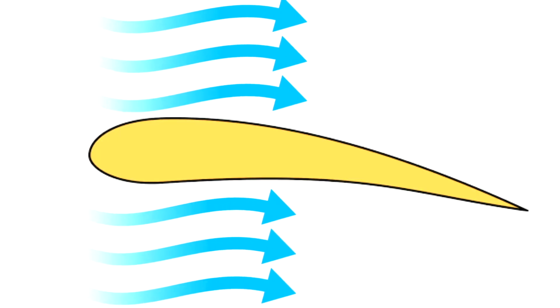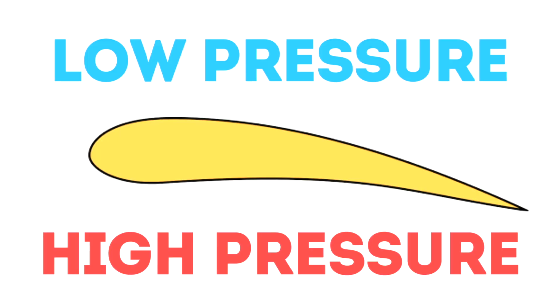So now when this happens, as you can see, there's a higher surface area exposed to the oncoming air compared to this left hand side. So when more air comes from this right hand side, it causes lift of the right wing. What is lift? Well, according to Bernoulli's theorem, when the air passes over and below the aerofoil, high pressure will build up below the aerofoil and low pressure above it. I mean, this aerofoil is a cross section of a wing. So high pressure below and low pressure above will cause a positive upward force because of the pressure. So that's when the lift happens.